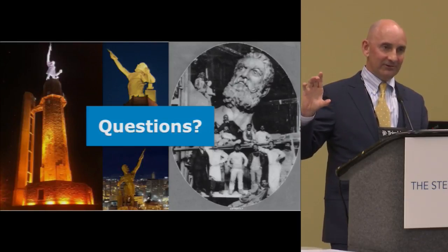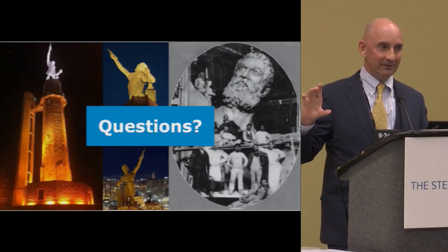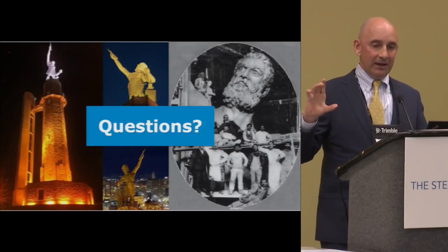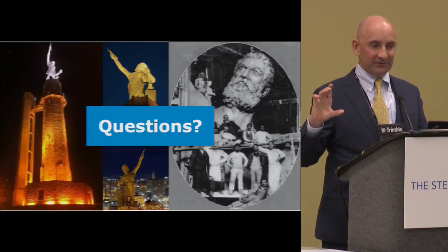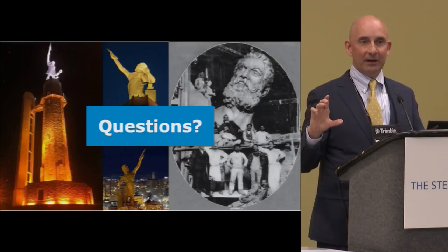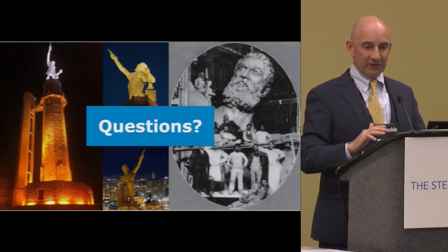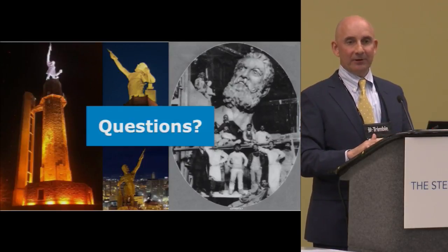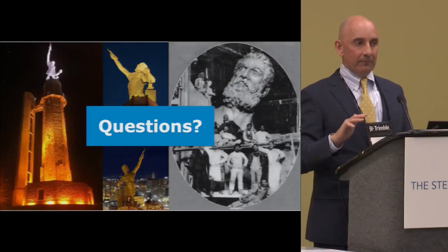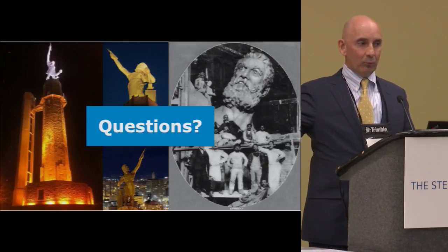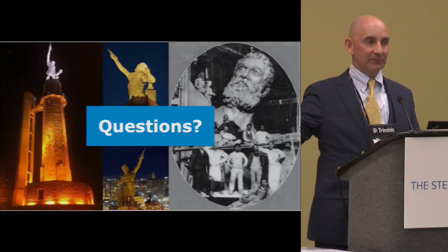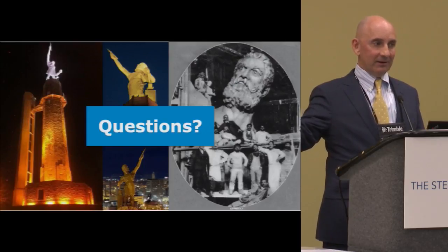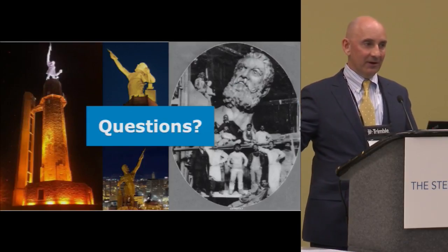So the interaction equations developed in that were for rectangular cross sections only. And the reason that they're different, if you look in that paper, it gives you an equation for the plastic strength under any combination of loads. But the problem is here, we have an interaction on stability, not an interaction on the plastic strength.